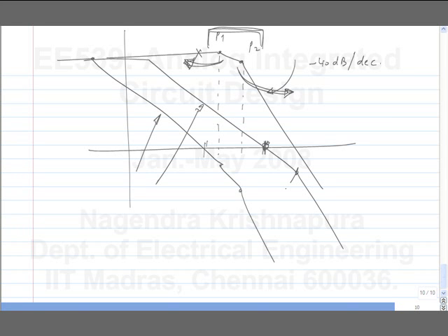Okay. I should not go and make an amplifier with a very poor bandwidth whereas a higher one is possible with the same power dissipation. Okay. It is in that sense that I say we have to increase the bandwidth, but what you say is true. Sometimes you want to cut out all the high frequency noise, and sometimes in fact the challenge may be to get a low bandwidth.